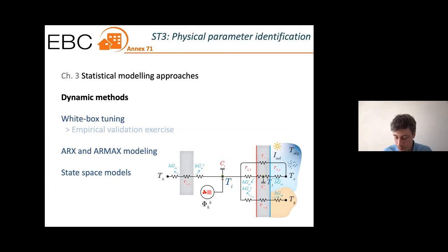If you want to explain the building's dynamic thermal behavior completely, you would have a distributed set of thermal nodes, an infinite number of them. But what we do here is we limit the number of thermal nodes, and we explain the heat exchanges that occur between them, the amount of heat that the different thermal nodes store, etc. So it's a simplified model which lumps the different physical aspects that come into play in a more simplified way.